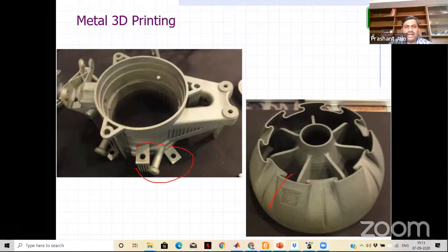You have very typical components here, right? So you require a typical casting. These are small components, joined by screws or some small welding. Material is poured, and after solidification, you have to break that casting. Then only these parts will come. Here, the advantage given by the additive manufacturing processes is that no pattern, no cast, nothing is required.